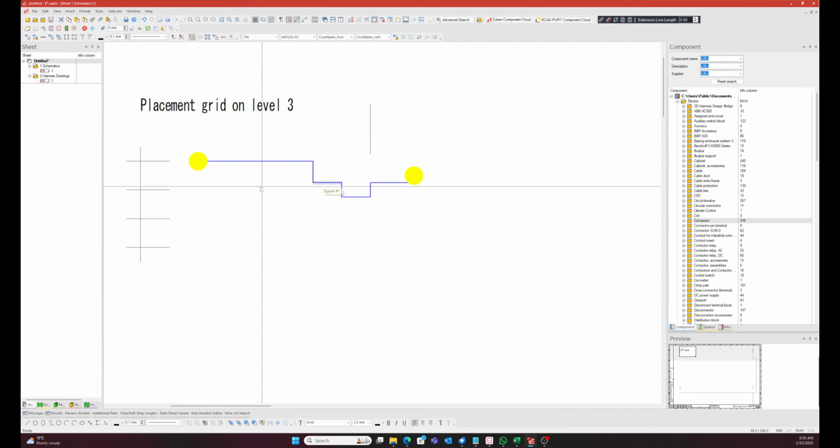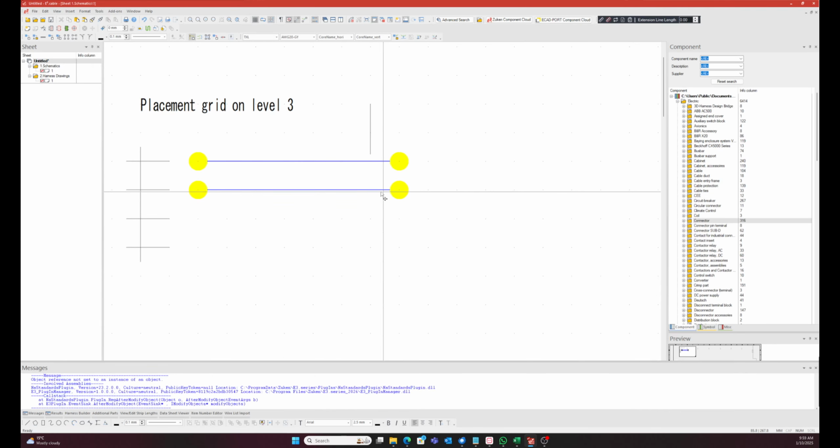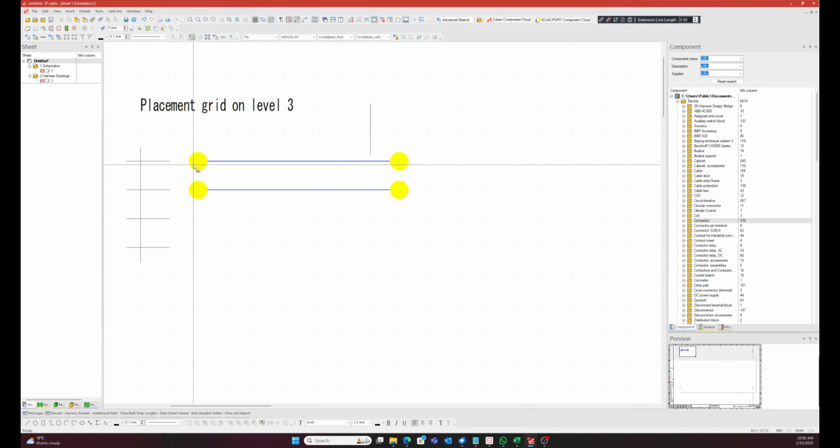When you do a 0, it means you can place it anywhere, and then all of a sudden drawing gets really messy really quickly, and things don't line up as you want, and they're tricky. Why you would use an alternate grid? Sometimes you have a wire coming between 2 points, and you've got a second, so if this is a connector here, let's just say, if you've got a second wire coming through, you might want to use the alternate grid and say you want something that goes, say, halfway there, or even slightly less than halfway.